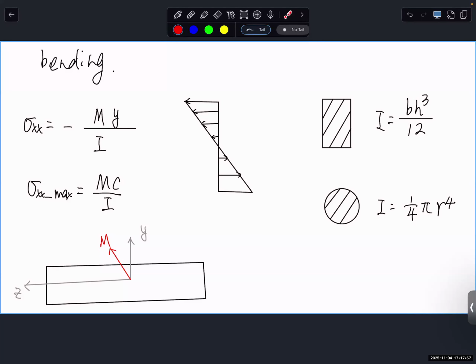If you consider, let's say, you apply this clamped reaction force and apply a force in this way, then it will generate a normal stress. And now this becomes the cross section. And what's the moment of inertia of the cross section? We can simplify this as a simple rectangle cross section. But if you go more complicated, we can calculate the moment of inertia. And y is basically whatever you have as the neutral axis, you consider this y equal to 0. Now this is y negative and that is y positive.